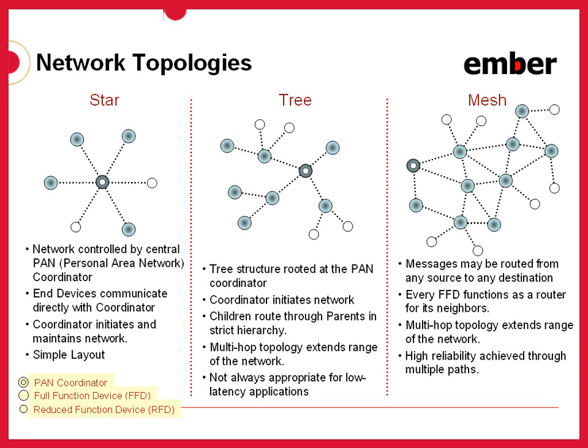This kind of redundancy and decentralization makes for a much more scalable network architecture with long-term reliability and adaptability. Note that while ZigBee networks can be constrained to a tree or mesh topology, all ZigBee networks have the potential to be mesh networks, provided there are two or more FFDs present in the network. And it's the multi-hop mesh networking capability that distinguishes ZigBee networks from other kinds of wireless topologies.